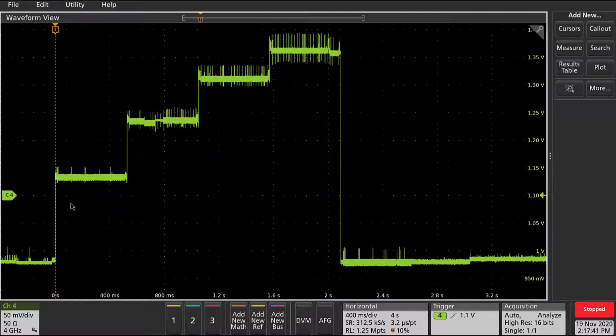So you can see our pattern is basically we're scaling to a higher and higher voltage value, and then once we decide that there's no more work, or there's not a significant amount of work to be done here on the processor, we go back into sort of our sleep mode, back down at 1 volt.